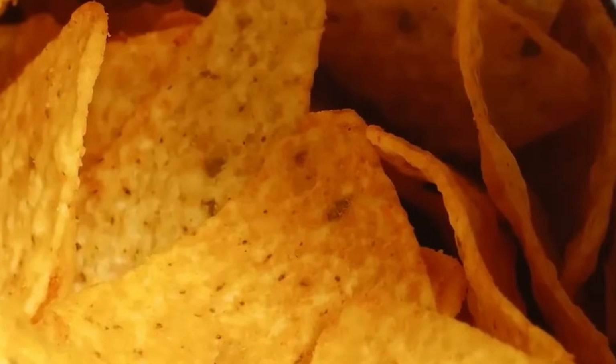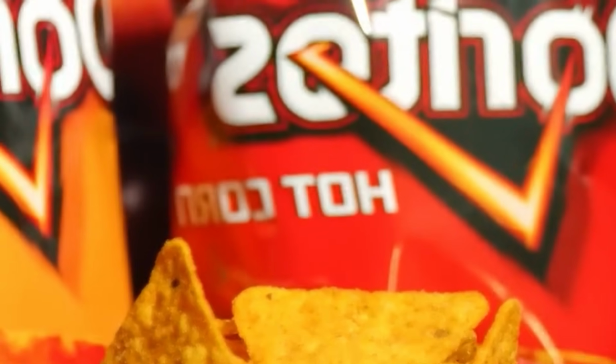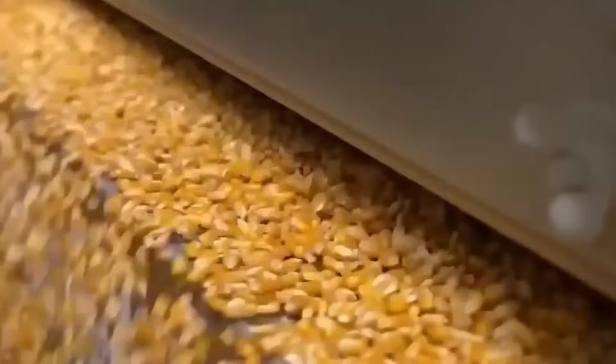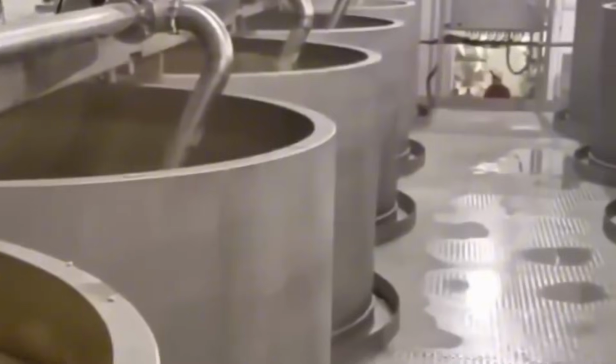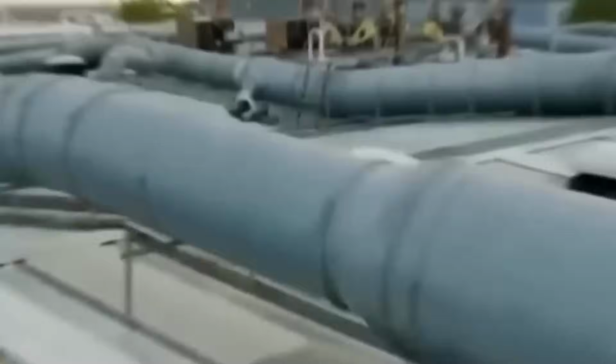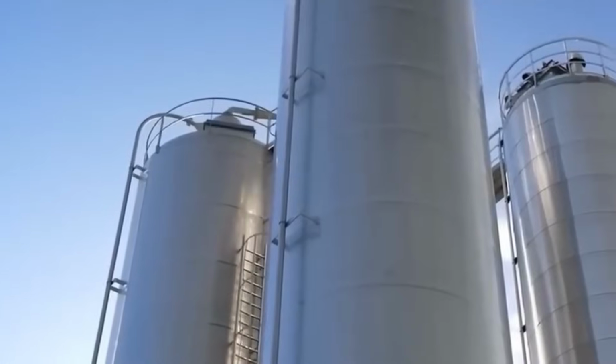Cartons are closed using hot melt adhesive applied by precision nozzles and sealed under pressure. Each box is labeled with batch number, expiration date, and a scannable barcode. Cartons are transferred to palletizing cells. Industrial robots, equipped with vacuum grippers or mechanical paddles, stack cartons in a predetermined pattern onto wooden pallets.